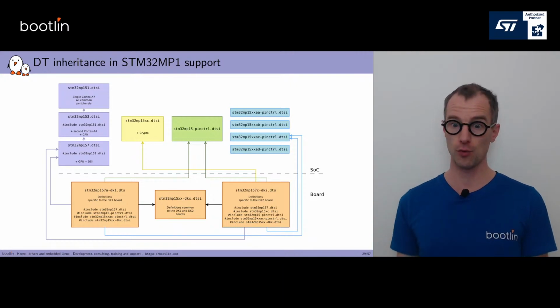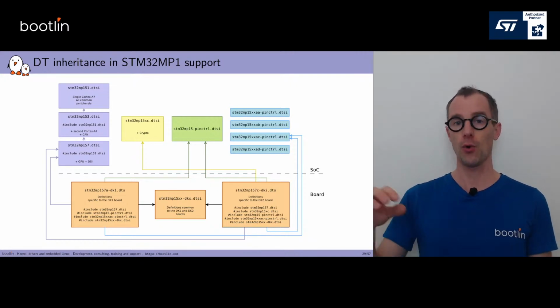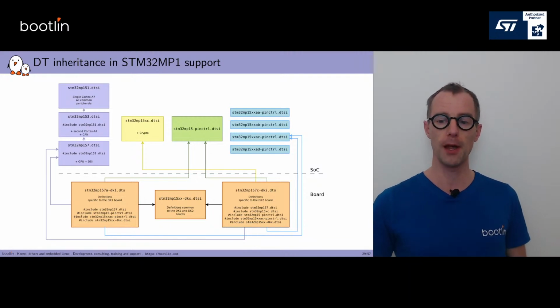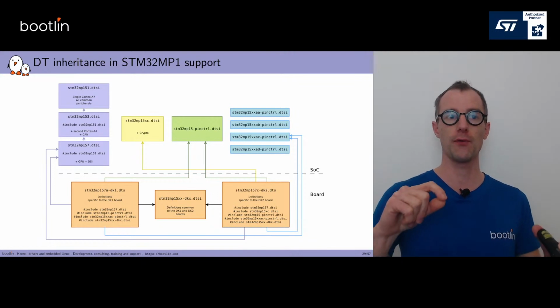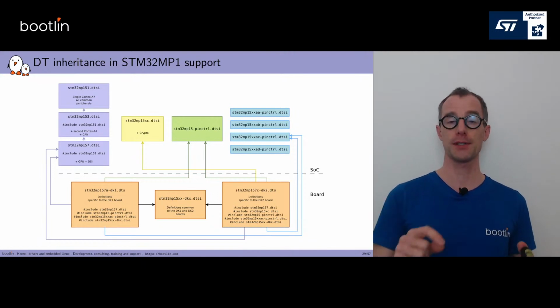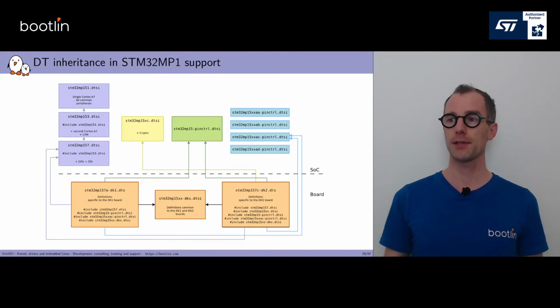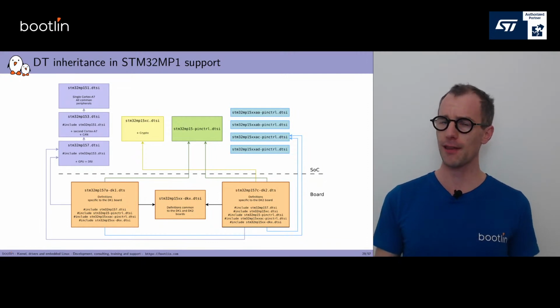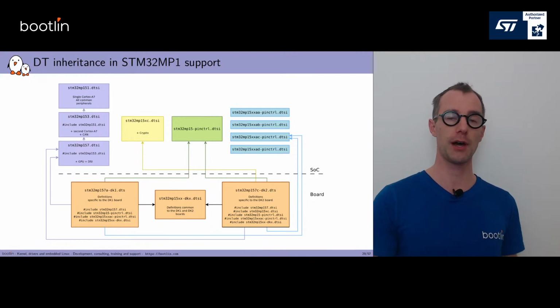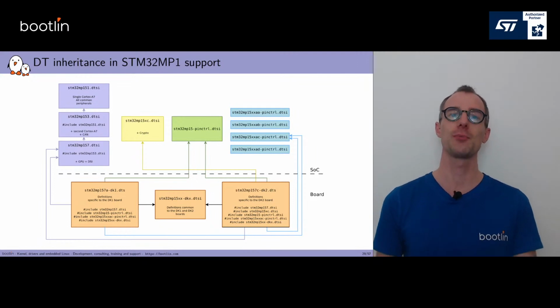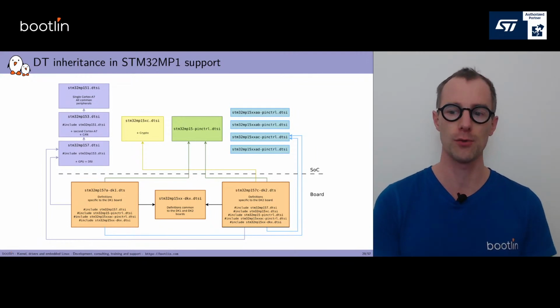And we'll get to Pinmuxing later on and how it interacts with the rest. The reason why we have so many blue variants is because in addition to the different variants of the SoCs that we have discussed, the SoCs are also available in different packages that have more or fewer pins and that expose more or less functionality to the outside world, changing a bit the set of GPIOs and pins that you can actually use on your board.